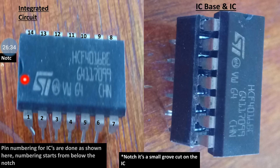Below the notch, the first pin is pin number 1, then 2, 3 and so on. Once it reaches 7 over here, the opposite of the 7th pin is 8, then 9, 10 and so on to the last pin. Hence, we can identify the pin numbers on an IC.